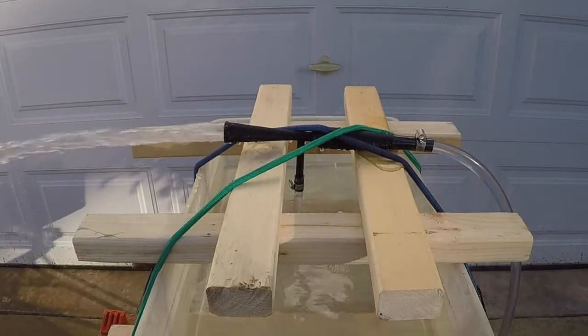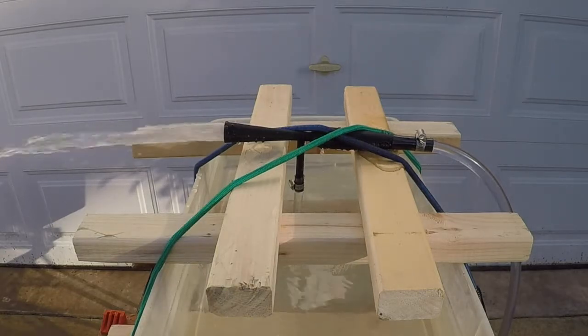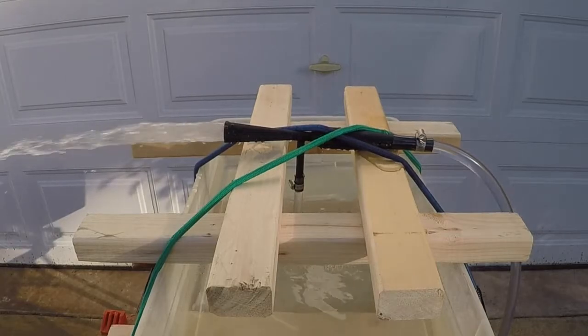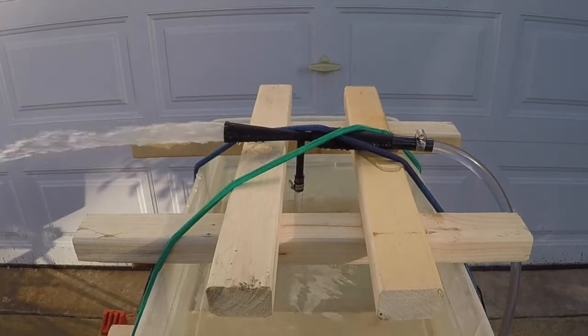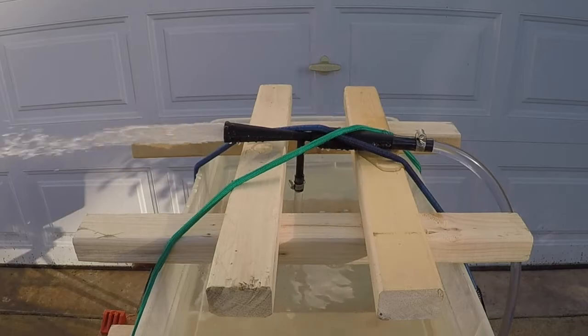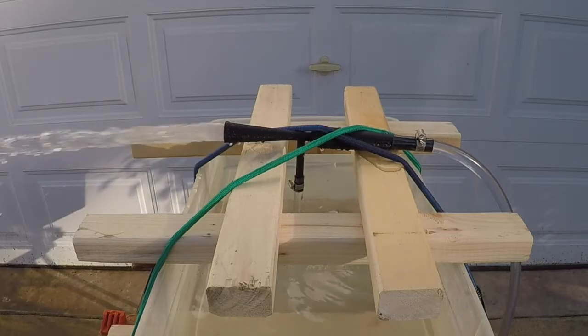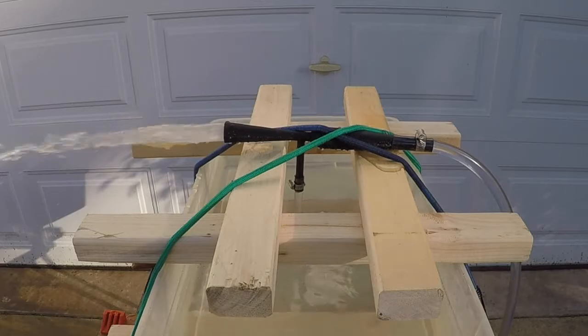It was almost like the Venturi was made of a porous material, and we came to the conclusion that it was just the way that it was 3D printed. So we determined that there wasn't a negative pressure being formed inside the Venturi to actually suck the liquid up like it was supposed to. So you'll see how we combated that issue and fixed our problem here in just a second when we move forward to our second test that actually did work.